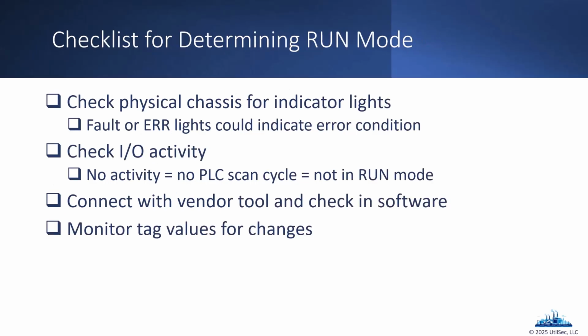So how can we determine if a controller is in run mode? Again, we consider run mode the quote unquote more secure. It's not perfect, not a silver bullet, but it is more secure. So physically, if you're in front of the controller, you will typically have an indicator light to tell you if it's in run mode or which mode it's actually in, even if it doesn't have a physical key switch or hardware switch, like a little dip switch.